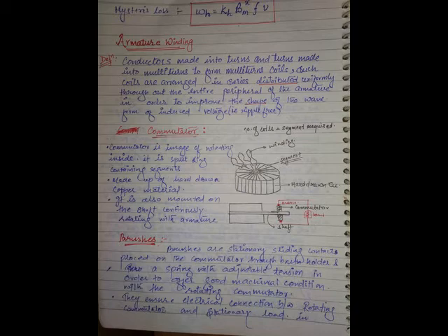This is one bunch of coil side, this is one bunch of coil side. You will have a high ripple content here. But if the winding is arranged in series, one after the other, then the voltage has less ripple content. So distributing the winding uniformly improves the shape of the waveform.